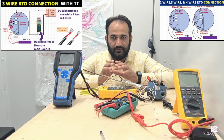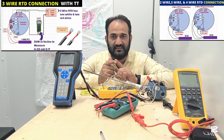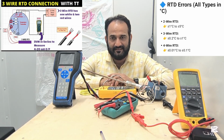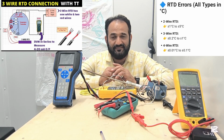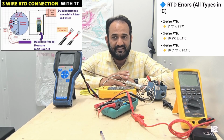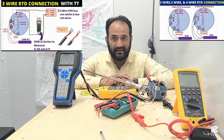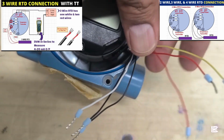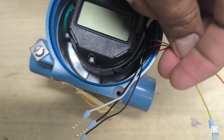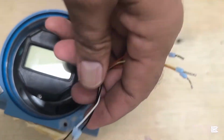If we use a 2 wire RTD, we must be aware that it will give us a 1 to 5 degrees Celsius error because of the lead wire resistance. And the 3 wire RTD is the one we commonly use. RTDs come as single element and dual element. As I will show you, this is a 3 wire RTD with a dual element.